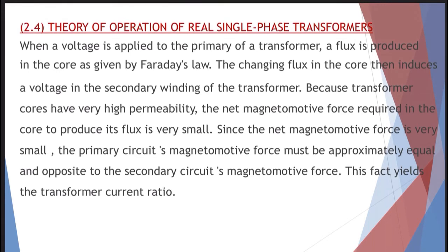2.4, theory of operation of real single-phase transformers. When a voltage is applied to the primary of a transformer, a flux is produced in the core as given by Faraday's law. The changing flux in the core then induces a voltage in the secondary winding.